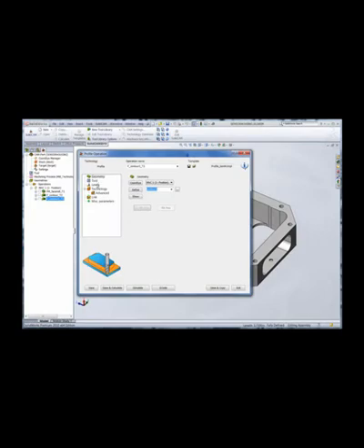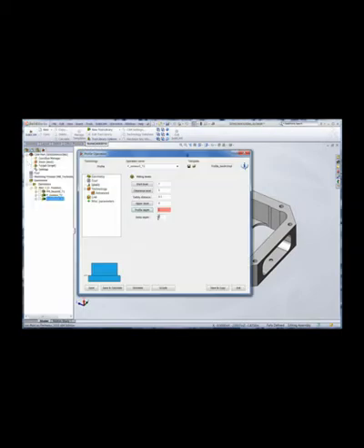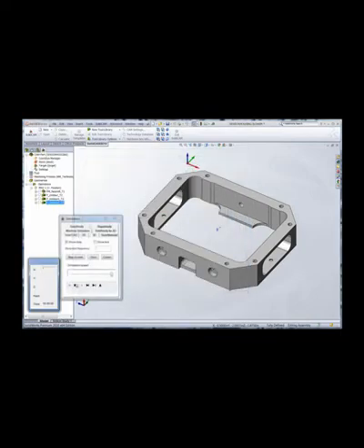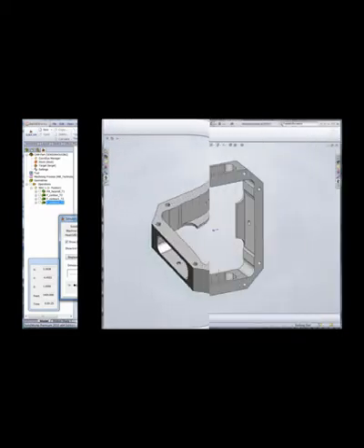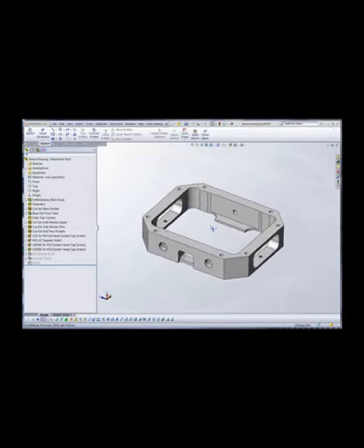Now I'll exit this, and we're going to start one more tool path for profile. We're simply going to load the template that we made earlier. Now all we have to do is define our geometry, the outer profile around the outside of the part. The tool is already chosen, so we're going to reset our levels. Our profile depth is going to be at this vertice at the bottom of the part, and we'll use our delta depth to add a minus 0.1 offset also.